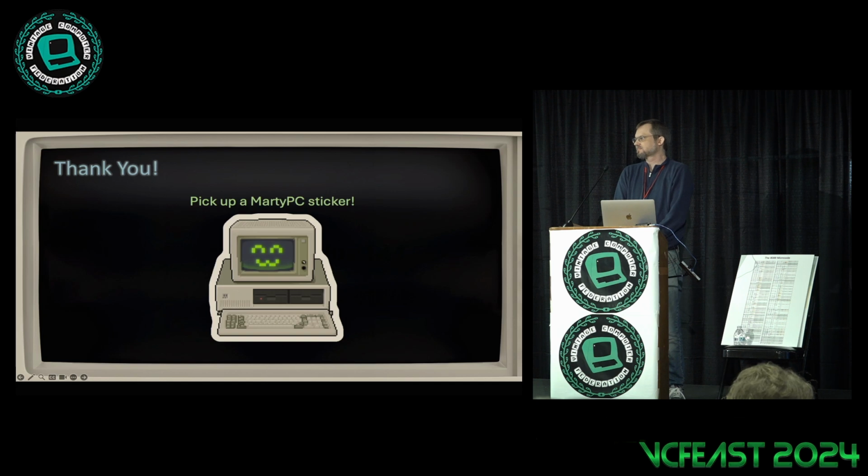Obviously, V20 has a number of instructions that are above and beyond the 8088, in addition to the 186 ones, but all of its own, homebrew proprietary ones. In the event that you want to do a V20, V30, et cetera, without having a Ken Shirriff decap and map, is there any clever way you'd be able to get the microcode for the non-Intel instructions?